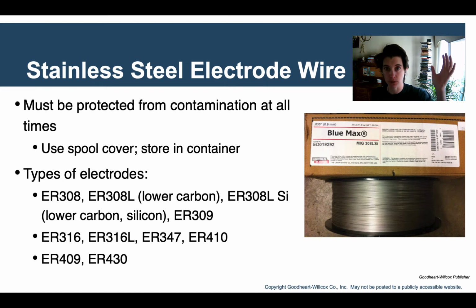That means you want to use a spool cover or store it in a container anytime it's not being used, especially if you're working in a shop where you're also welding carbon steels and you might be grinding carbon steels and all that's going out into the air and can settle on your electrode wire, because that would totally ruin it. That would make it not stainless anymore.